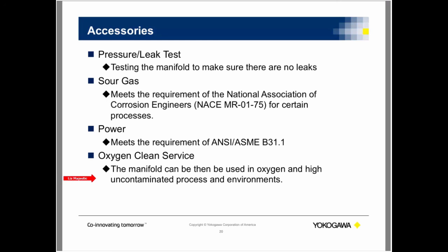When they come out, they're generally in a bag, they've been labeled, they've been cleaned. Your technician will generally handle these in gloves, and your transmitters are also oxygen cleaned too. So you don't want to contaminate your manifold at all. If it's been oxygen cleaned, a lot of technicians usually handle it with gloves, and they don't touch the manifold at all. So that's one key thing if you do get oxygen clean service.